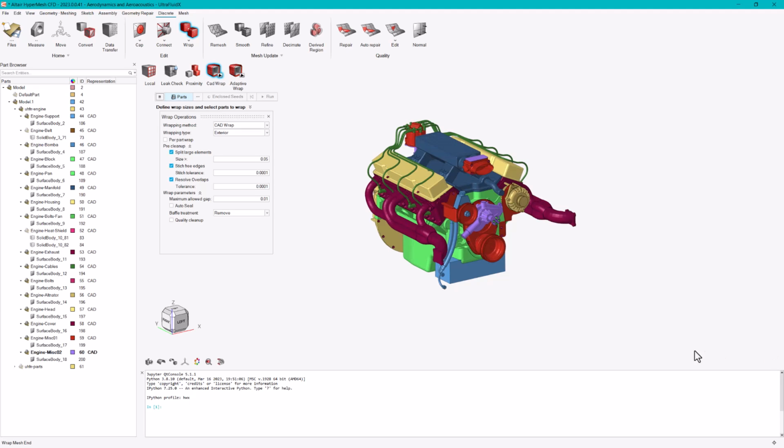Once the wrapping process is finished, it will display wrap mesh end at the lower left progress bar location. Then what you need to do is right click in the empty space and then click the green check mark to finish the wrap and confirm this operation.